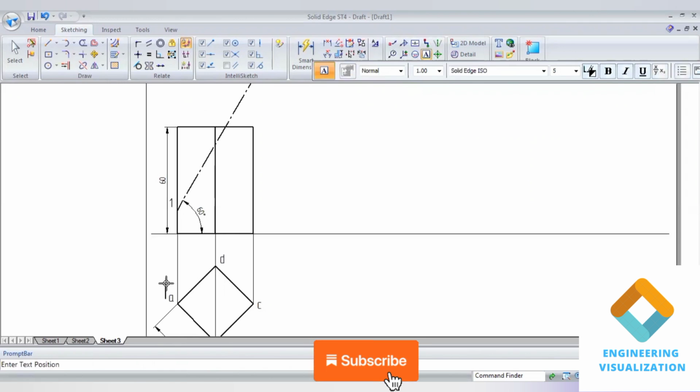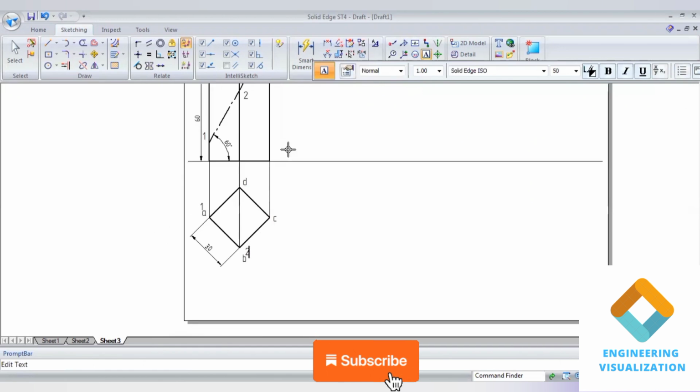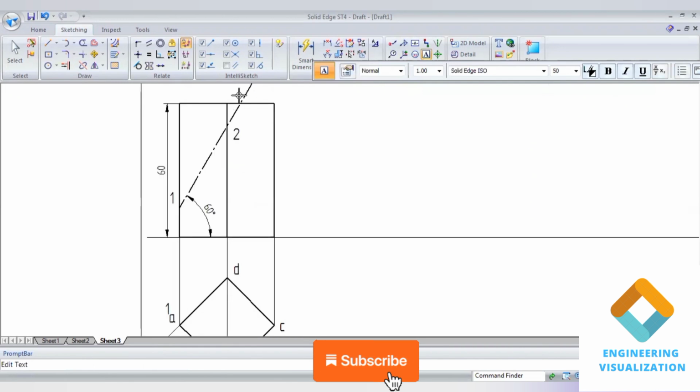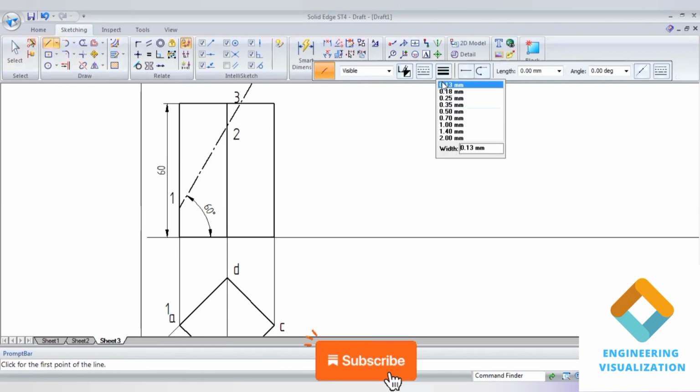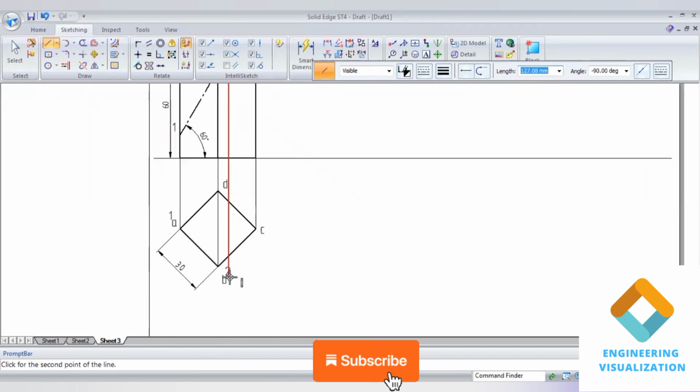Now we can give the naming here. Point 1 is where it is cut, on the A edge. Point 2 is falling on the vertical edge B. Point 3 is not falling on C, it is falling somewhere in between B and C. That's why I'll be drawing a projection line from this intersection.